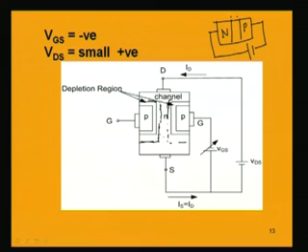So in order to have a drain current flowing, we must have gate to source voltage greater than that pinch off voltage. So every JFET device will have its pinch off voltage specified. Now if you go on varying the gate to source voltage, the current will be going on reducing and reducing, and it will become 0 when it reaches the pinch off voltage.